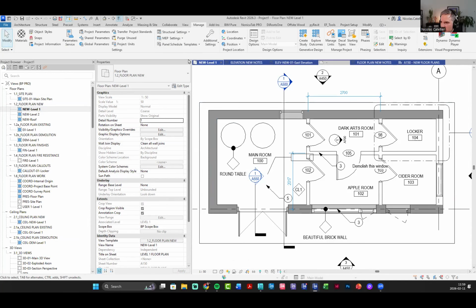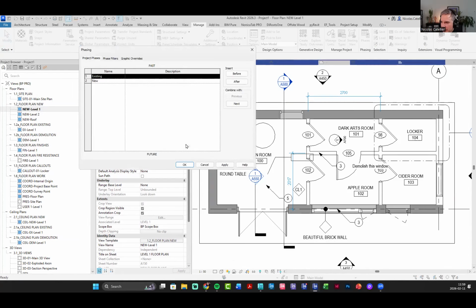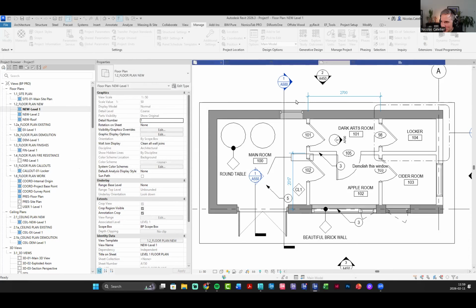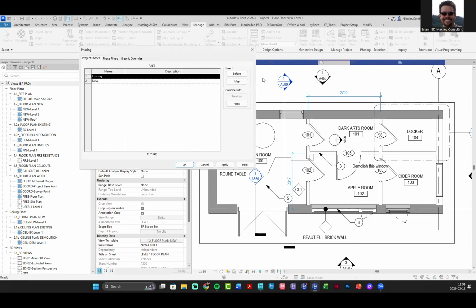So for people wondering what we're talking about, that would be creating a new phase, whoops, I put it in the wrong spot. I'm always worried about adding a phase in a project, but you would call a phase called legend. And I always do it at the end, so you're never going to see it as something existing. So you put it last, afterwards. Yes, because that way, if I'm on a new construction, I won't see it as something existing.